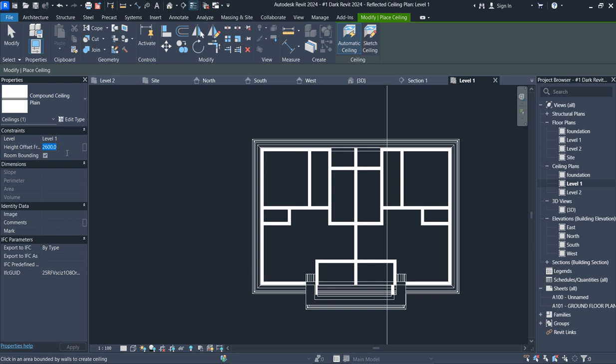So change the height. The first height you need to do is 2850. So change that particular height. That height is going to be synonymous with everything. So when you are doing the work, you continue rippling one after the other. So you can do it by saying, let's just click, pick walls.